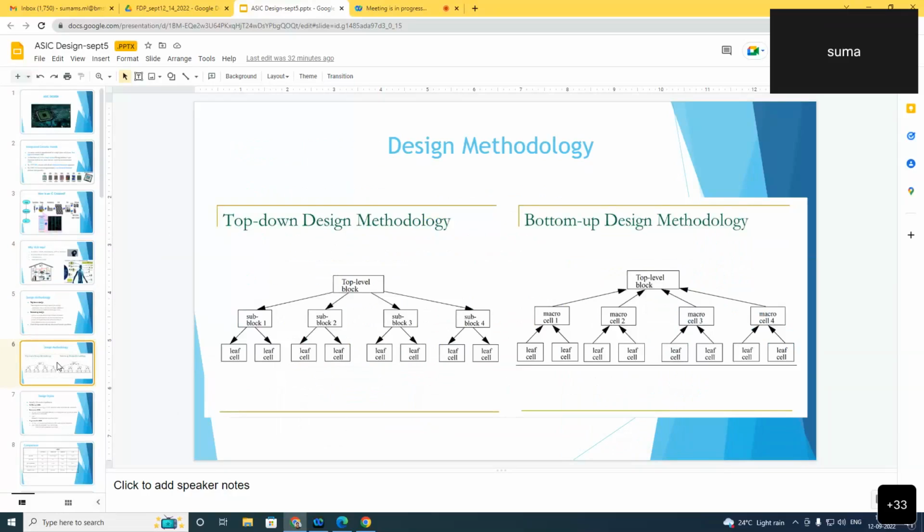So we can see the block diagrams with respect to the top-down or bottom-up design methodology, where in top-down design, we realize the desired complex behavior of a hardware by partitioning it into an interconnect of simpler sub-behavior, and hence we create lower levels of abstraction from the upper level. So we go from the upper level and then come to the leaf level or a leaf cell.